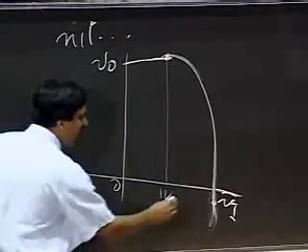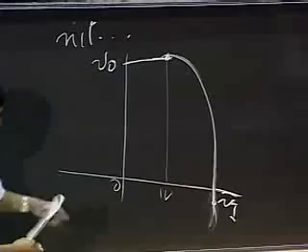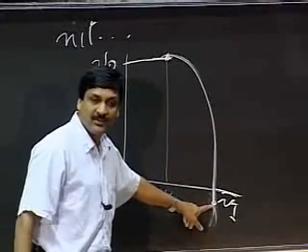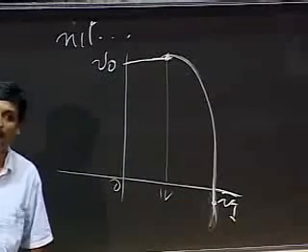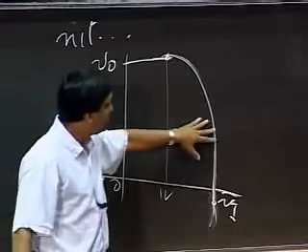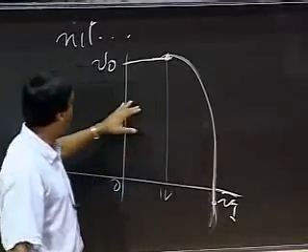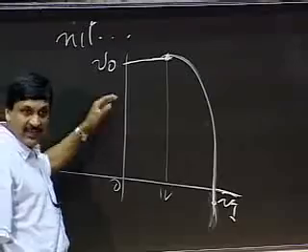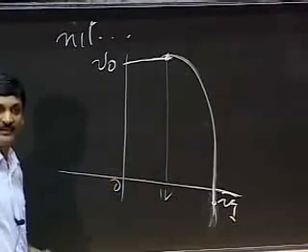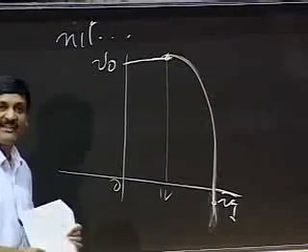The point down here says that the output has gone negative. This is 0 here. The output has gone negative, and my current source is still supplying a current. Up here, the voltage across the device is positive, V0 is positive, and it's supplying a current, so it's consuming power. It's burning power like a resistor, like all bad little resistors do.